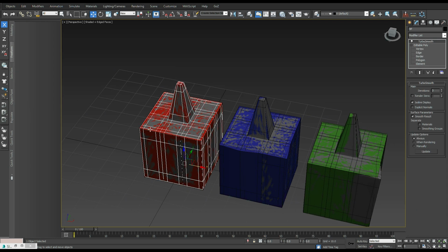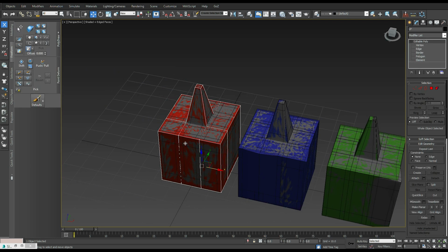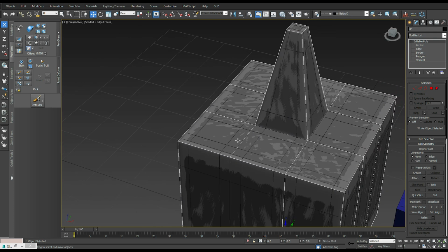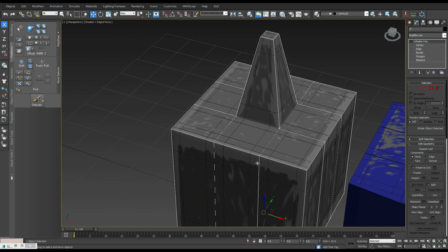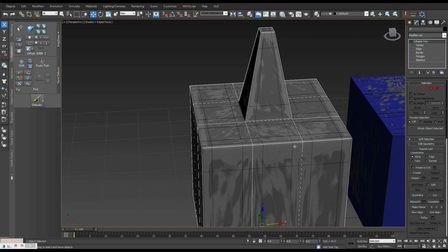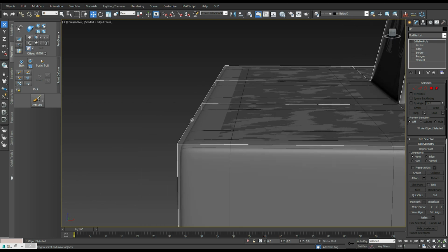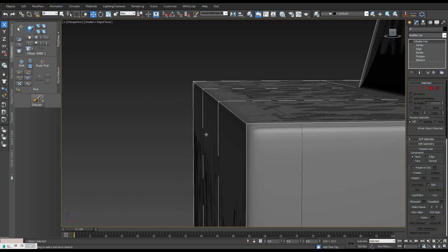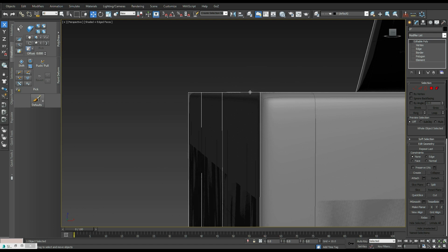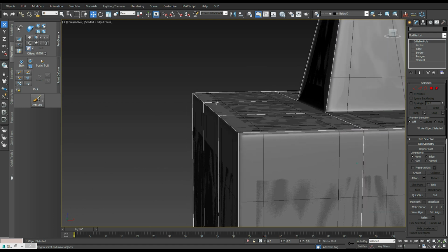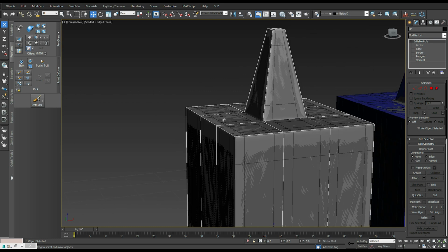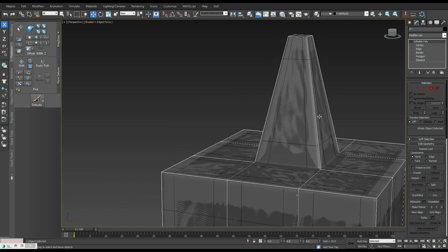But going back to the first one, I'm going to grab onto the low poly. I'm going to hit Alt-X on my keyboard to go into X-ray mode. And we're going to zoom in on the edges, because with a hard surface setup like this, the edges are what's really critical. It's what we're looking for. It's what's going to give you that nice smooth high poly look on your low poly. But if you take notice, look how closely and how exact the low poly edge is in comparison to the high poly. When it's set up like this, it's going to give you that nice smooth bake transition across the low poly mesh. So when the camera's zoomed out, it'll give you that illusion that the thing is much more detailed in high poly than it actually is.